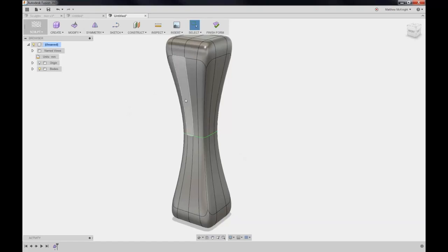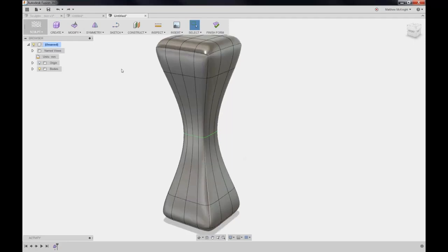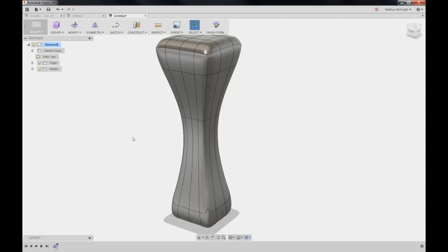In this instance, note that it's transferred them from one end to the other because we are working with symmetry. So to end symmetry, I can clear the symmetry, which will turn that off, and then gives us the ability to then just modify a group of edges like we have there. So in this case, we've removed the symmetry, deleted a string of edges, and now we've got some geometry that we can use to further our design.